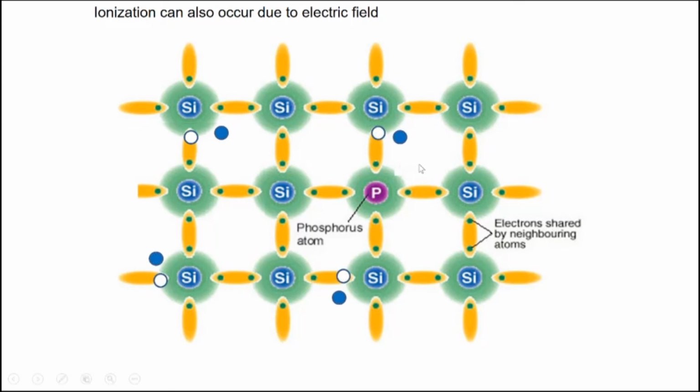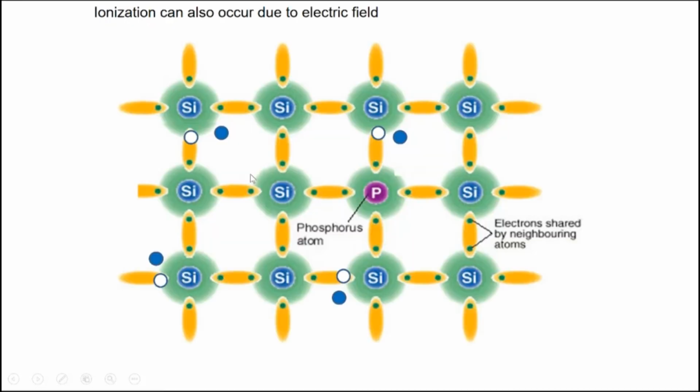So large electric field ripping, something similar to breakdown that may occur, let's say, between two plates, an electric arc kind of a thing here. So that's a different breakdown mechanism in the sense that an electron is not gaining energy from the field and knocking out an electron hole pair. That was called impact ionization. This is what we call field ionization. Both are due to fields, but a different mechanism is there.